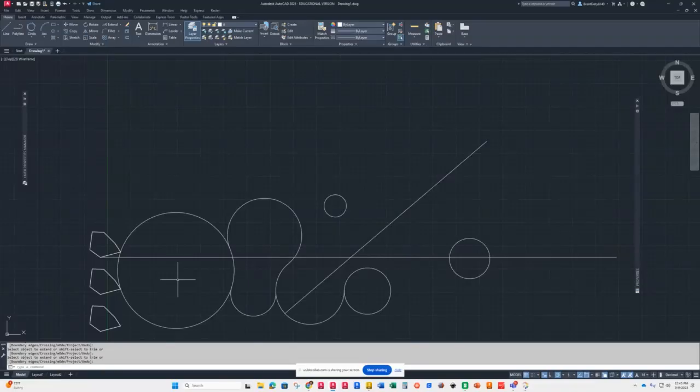That was a bunch. Well, what I could do is I could pick this guy over here, go to extend, and then just pick that line, and it'll go directly over there. So it's like trim. You can do a precise extend as well. You know, why waste your time clicking and clicking when you could just pick where you wanted it to go the first time and send it there.